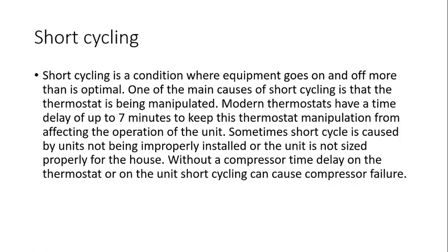Short cycling. Short cycling is a problem and can cause irreparable compressor damage. Normally you see short cycling, at least in the past you did, with a compressor that turns on and off because people are manipulating the thermostat to work better. Those were the old mercury thermostats or bimetal thermostats that you could do that with. Now modern thermostats have a 5 to 7 minute time delay before the compressor turns on when someone changes the temperature. So that way that compressor doesn't turn on and go off, turn on and go off.